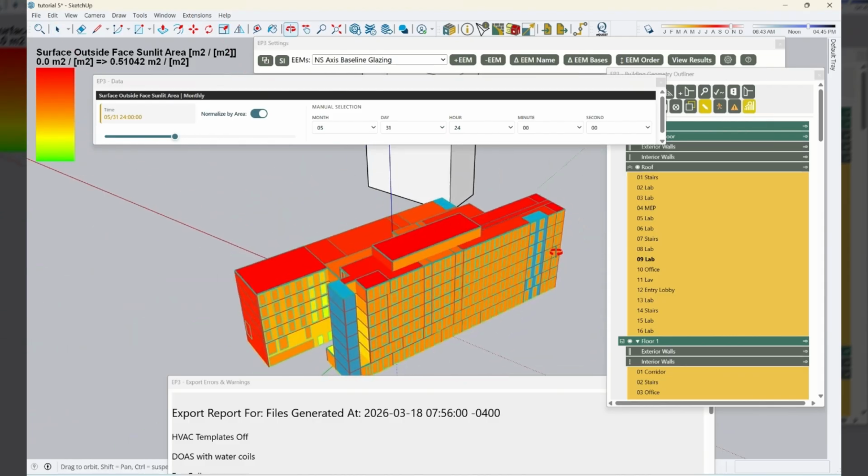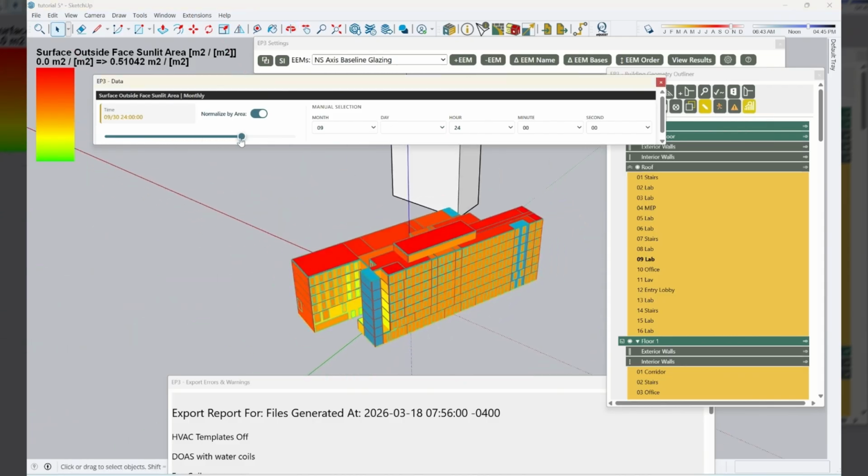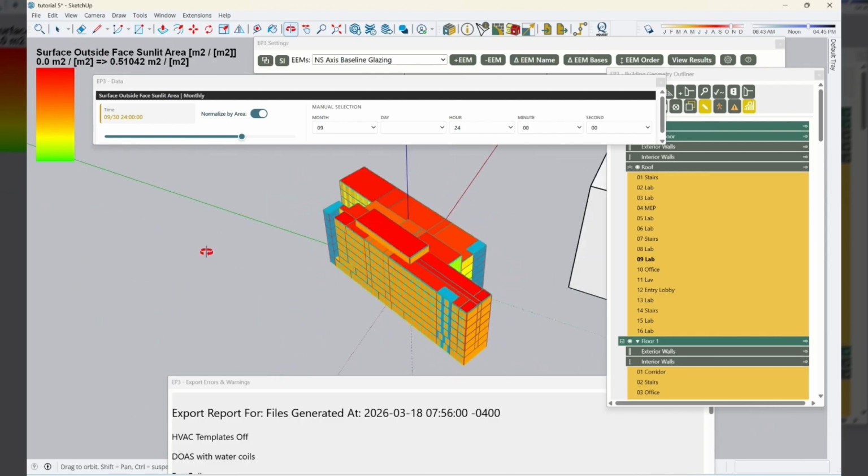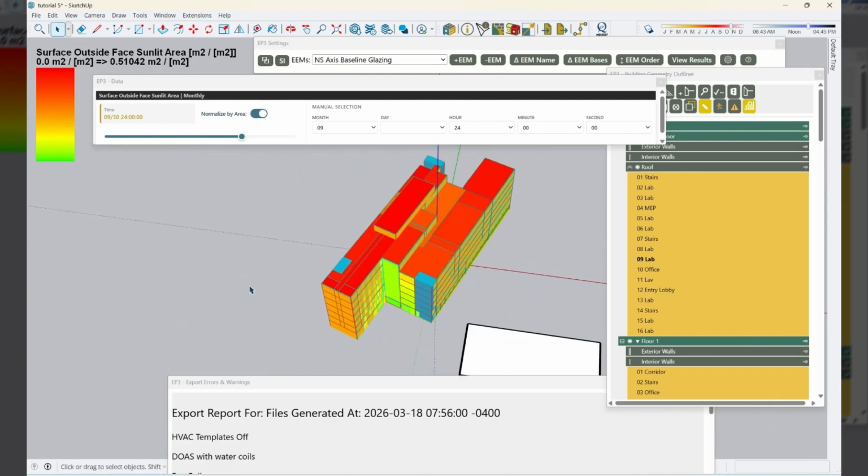So that might be a way to inform tuning louver locations. If you were looking for cost-saving measures and you wanted to, say, remove some of the louvers in a location that will have less of an effect on the ETTV and less of an effect on the building energy use and overheating potential, you could take a look at maybe removing the louvers on these two small portions of the building because there's some self-shading of the building going on there.